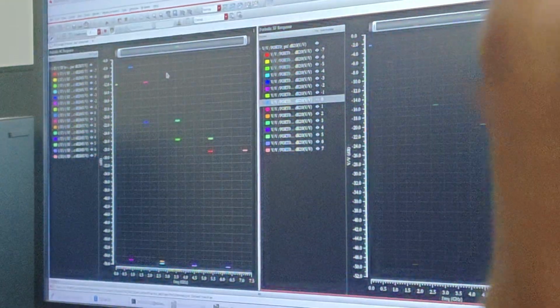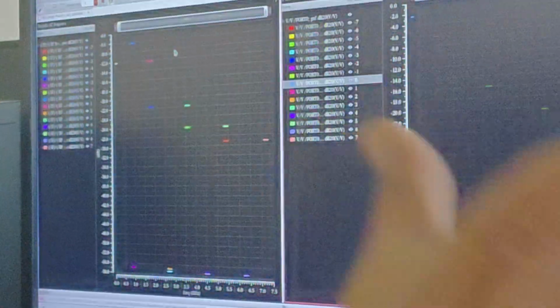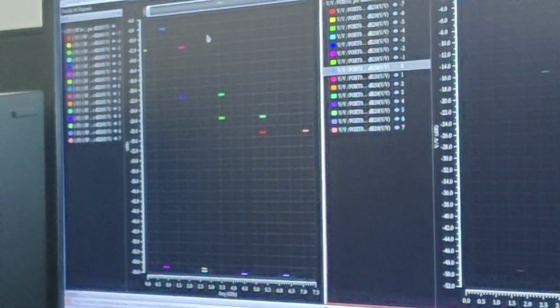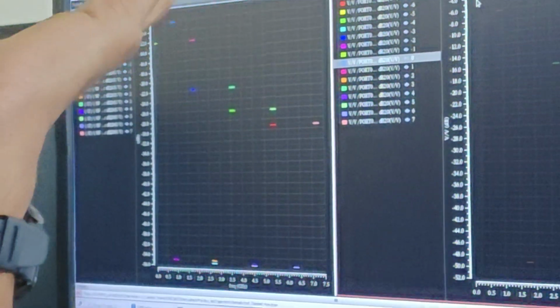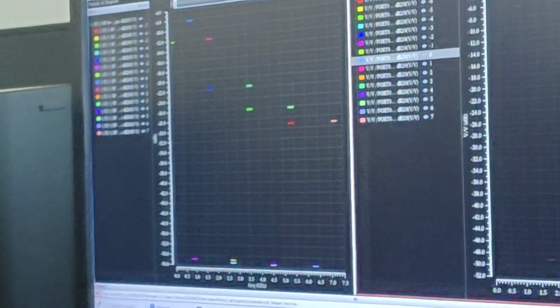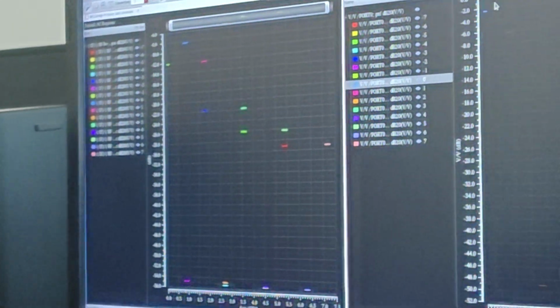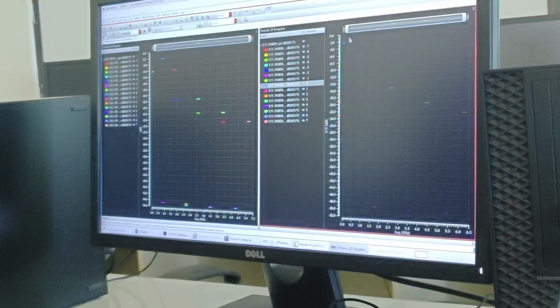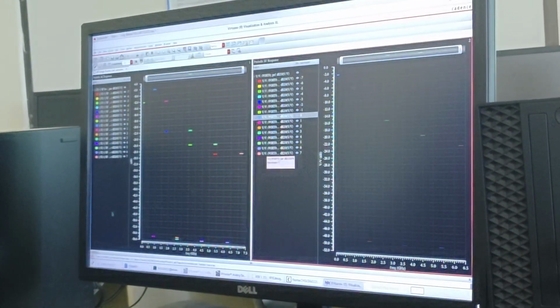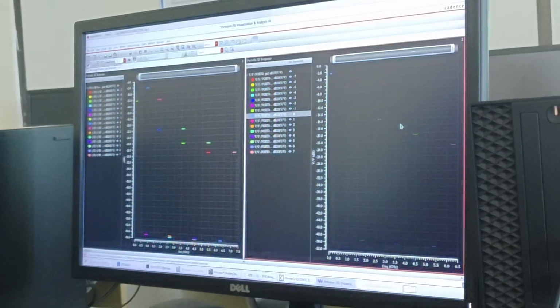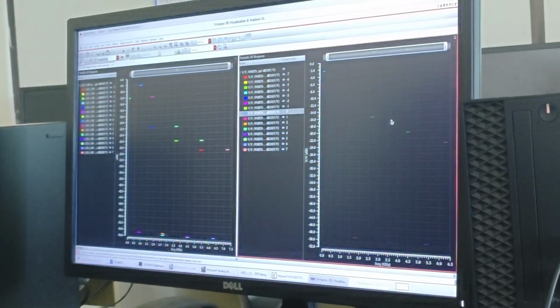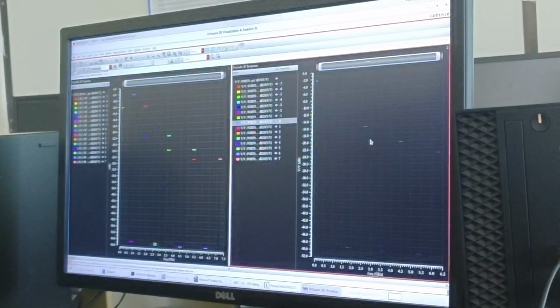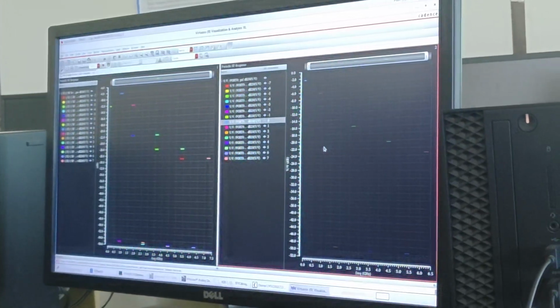But if you want to see exactly, PAC analysis is more clear. You can select this node to this node and see how much conversion gain you get. So that is exactly clear. But if you want to see with respect to the output scale, then you can do PXF analysis also. But mostly we will go with PAC. It will be clear; you can select nets anywhere, and those conversion gains will come. So better to go with PAC. PXF is also helpful sometimes, but do that analysis when you are clear about what you are doing.